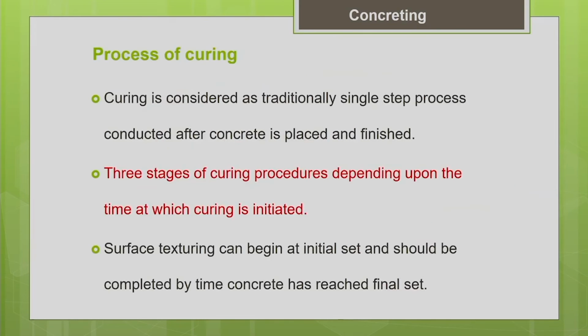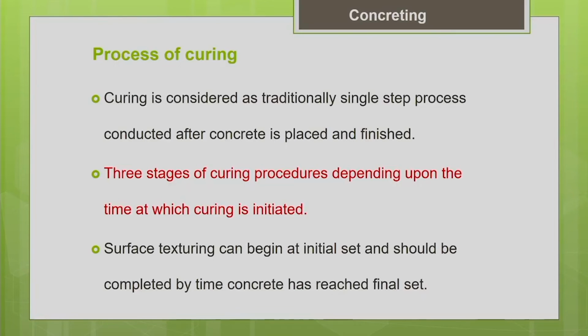Okay. So, the process of curing earlier was traditionally considered as a single step only. Very commonly we do the curing operation after the finishing of the concrete. Mostly after the concrete attains its final set, we start applying water to the concrete for curing purposes. This is a traditional method. But nowadays we do the curing also in stages. I will tell you why we do it in stages later.